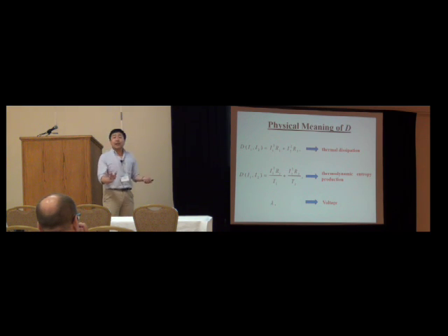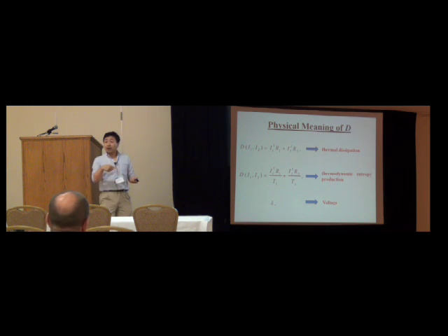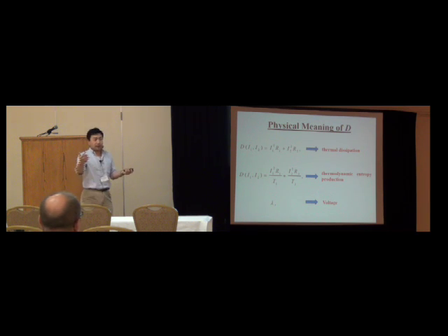Interestingly, there's nothing special about formulating this problem in terms of the current. You can formulate it in terms of voltage. What you get corresponds to the problem of two serially connected resistors. If you have a total voltage, what's the individual voltage of the two? You get the same thing: the voltage is proportional to the resistance. And the Lagrangian multiplier there is the current, which is constant. Of course, in serial resistors the current is constant. So it is quite intuitive.